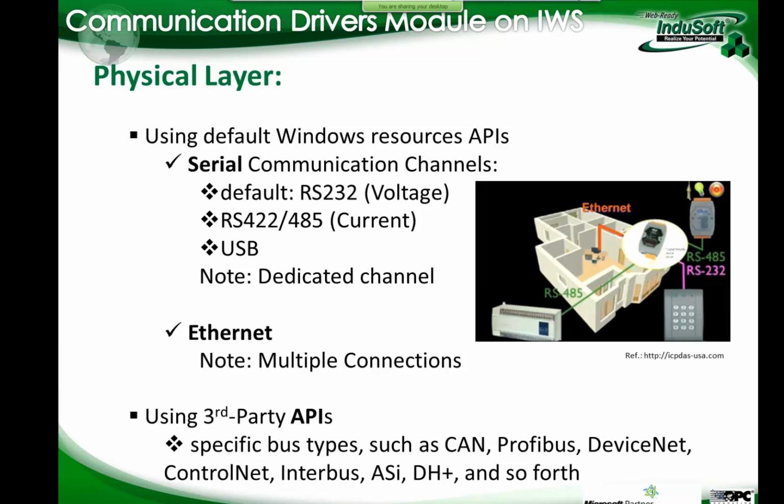Most of the new PLCs, they come also with USB ports, but it's gonna take a while for RS-232 to just disappear. So it's still very popular to have adapters from USB to RS-232 for PCs, and several Windows CE HMIs, they come with RS-232 port. It's almost mandatory to be able to talk to PLCs, low-cost PLCs without Ethernet channels. You're gonna go through RS-232.